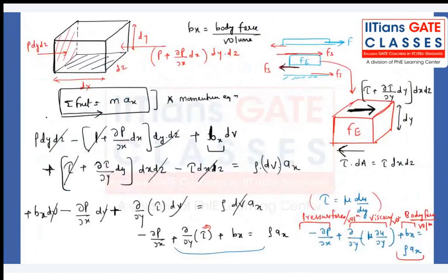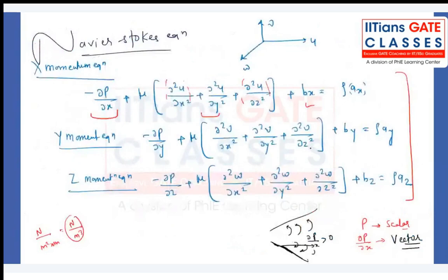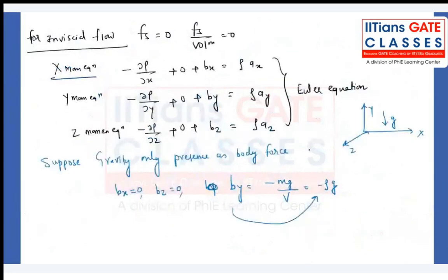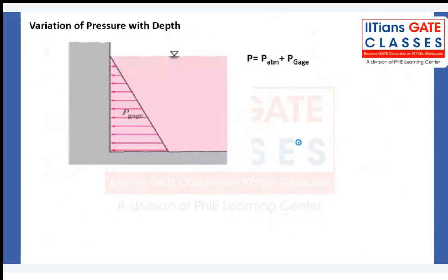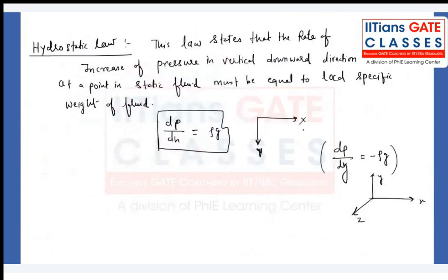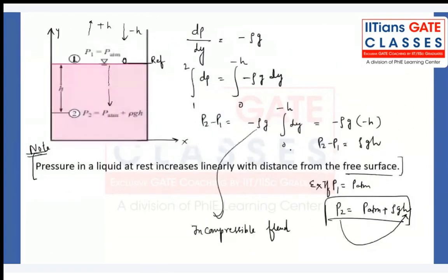And what is the condition for that? Newton's second law definitely has to be applied to some particle, a single particle. But we are able to apply it to a control volume just because we should be thankful to RTT. That converts the necessity of basically the system to the control volume, right? Getting my point? Even you can derive the Navier-Stokes from an RTT equation also.